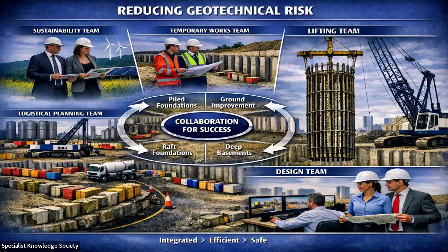So yes, is the answer to the question. You can put sound shrouding around, because driven piling is typically more noisy than rotary piling. It's interesting with rotary piling, the biggest noise seems to come from when you're spinning off and you're getting clanking of steel on steel, rather than when you're drilling piles. But for the displacement piles, the driven precast, the driven steel piles, yes, you can shroud, and it does minimise and help the noise.